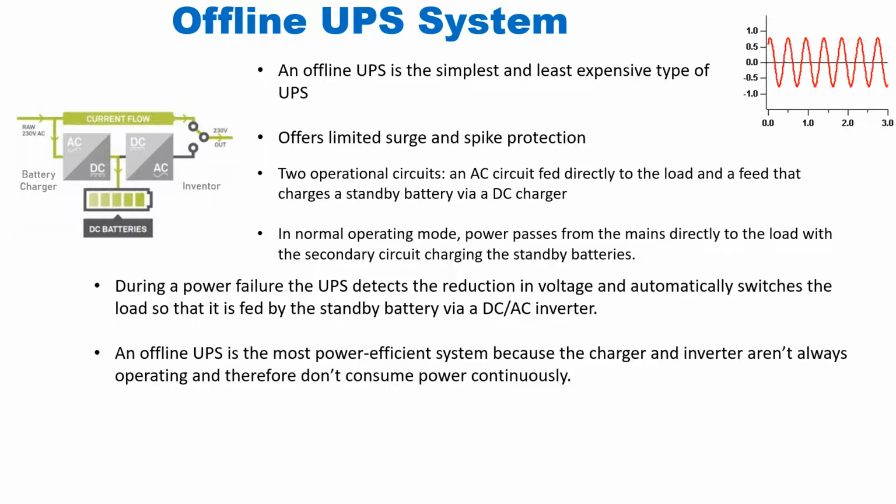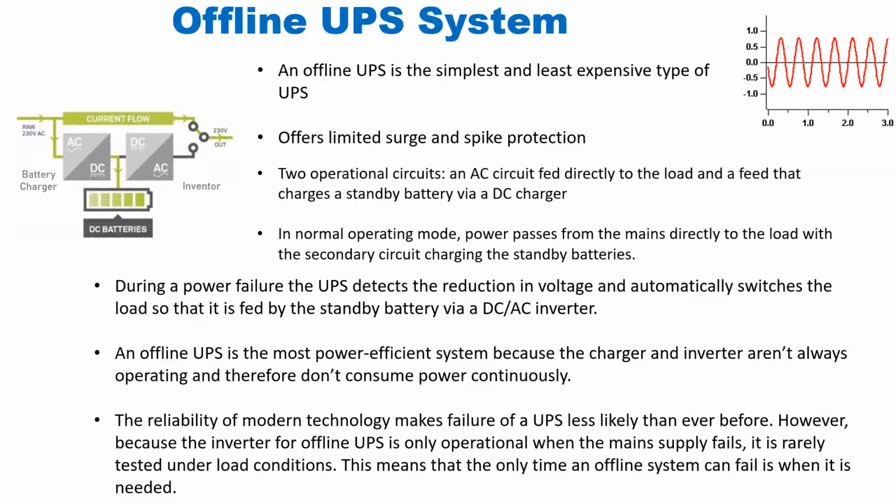So like I said, this is a drawback, because when the power goes off, or the voltage goes below a certain threshold, that's when the circuit starts working, and that's when you would realize if there's something wrong with the inverter circuit. So that's a big problem with the offline UPSs.